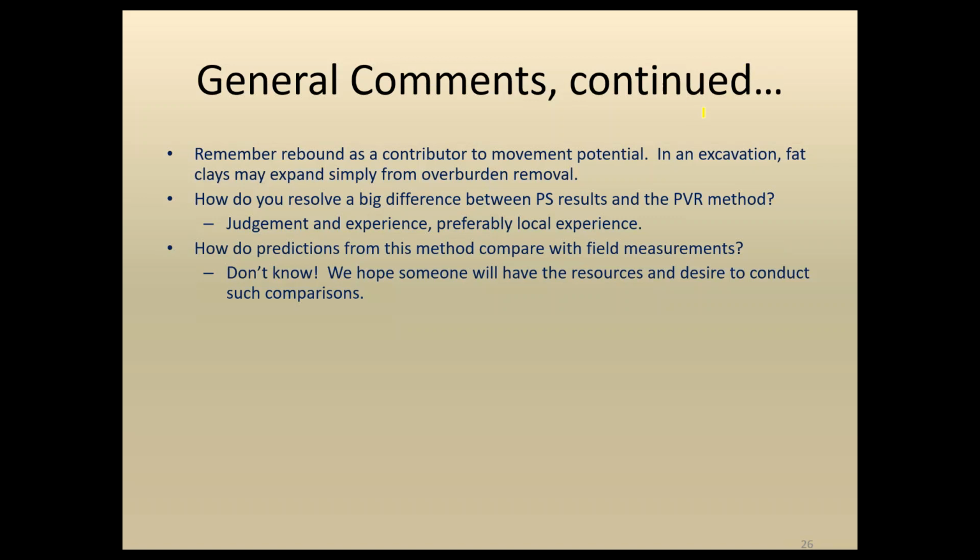So one might ask, how do you resolve a big difference between the pressure swell results and the PVR method? I guess my response would be mostly judgment and experience, and preferably local experience. It can be disconcerting, certainly, if one runs PVR calculations and swell tests, and the swell tests are twice those values. It requires some thought.